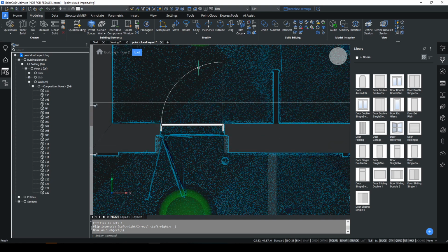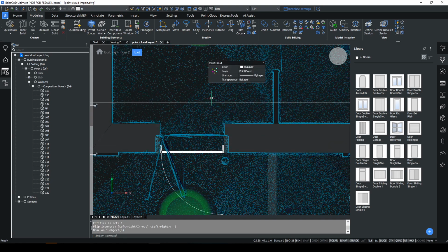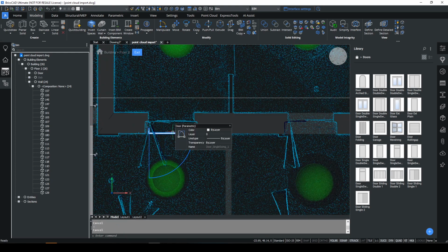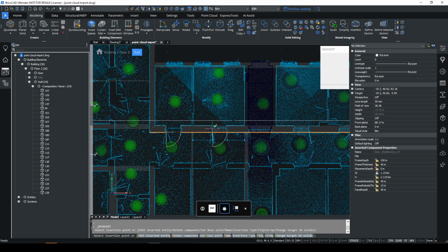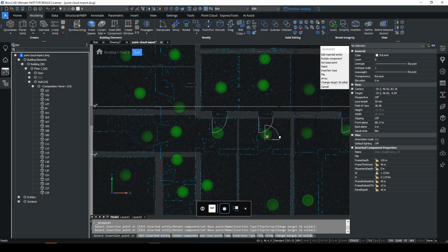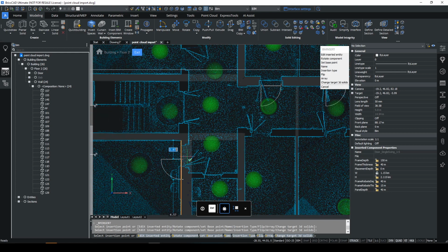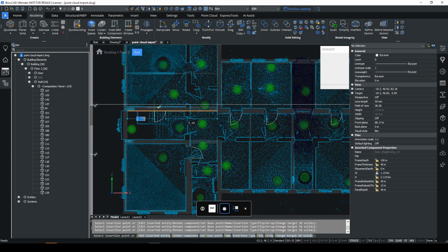And all you would do in this case is, if it's a situation where there's multiple versions of the exact same door in the building, you will get one done correctly, hover over that, and use the BIM insert command to effectively copy that, and then just move around and place that in all the relevant locations around that building. So again, I'm not too concerned about getting it accurate at this stage. I want to just show the concept. So we just place a few of these in here. I'll just do one more up here, for example.